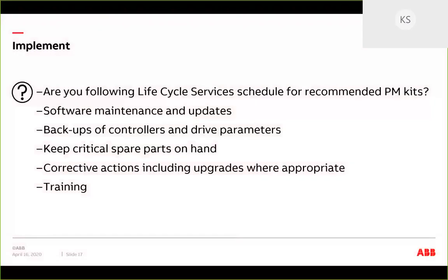Implementation is really just what this says. It's implementing corrective actions, whether it be software and maintenance, backups, or your critical spares. They can come from you. You live with this. The customers could say, hey, something's funny with this. Okay, that would go on the list. Or we use an ABB person that has a rotation and says, hey, something's not right, through a preventive maintenance plan. Or maybe we use data-driven, where the data is forecasting issues.